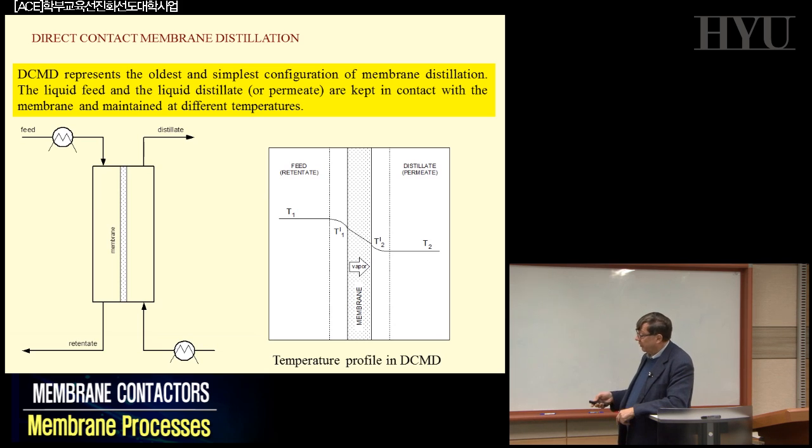What is important, however, is that here you can operate at any temperature. You can evaporate water even at 20 degrees centigrade. Few molecules, but you can do it. And if the number of pores is billions and billions, if you have a nice membrane surface with a nice distribution of pores, the fact that there are very few molecules per single pore can be compensated by the fact that you have billions of pores. If you multiply each pore by the number of molecules, you have a significant transmembrane flux.